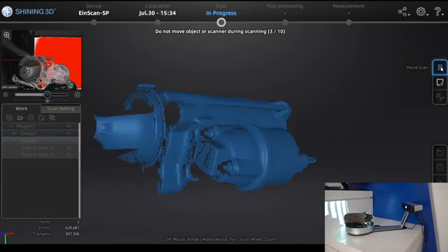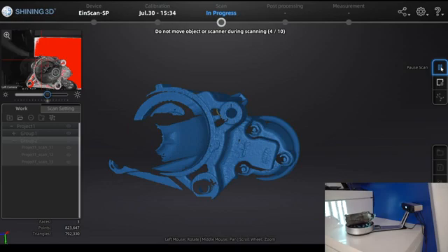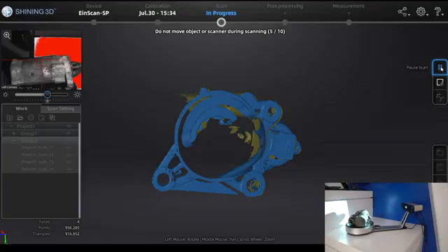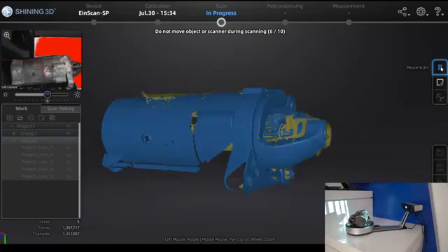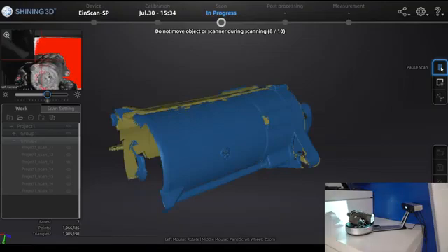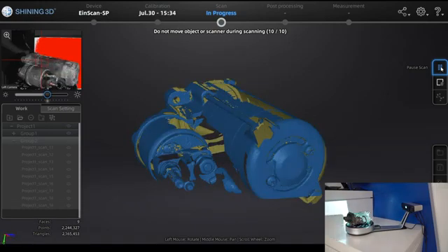For sure, for this one you can also choose less. As you could see, you can also choose more depending on you, also depending on the part. And once the scan is done, the software will try to align automatically these two different groups together if the scanner has seen enough features, enough overlap area. And then you have the options, either it will do it automatically, or if there is not enough overlap, you can also do it manually.